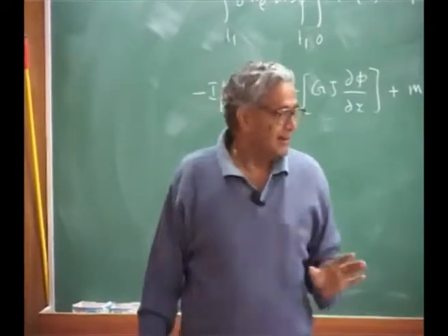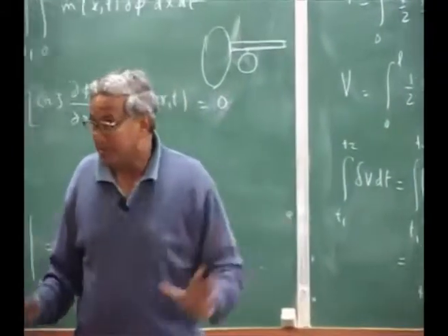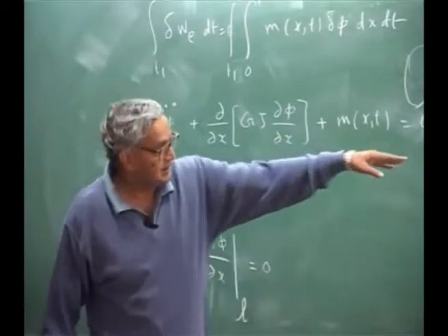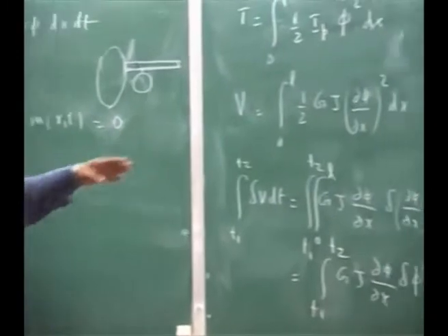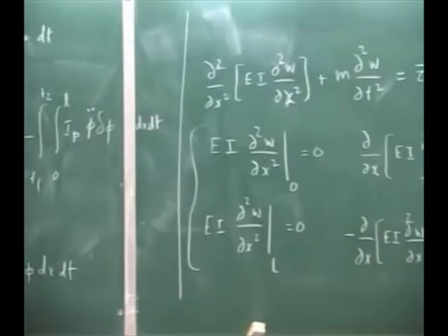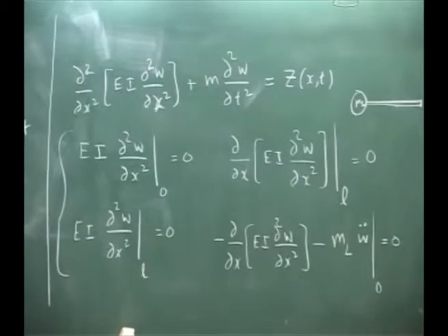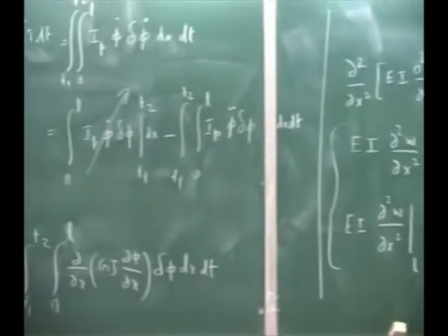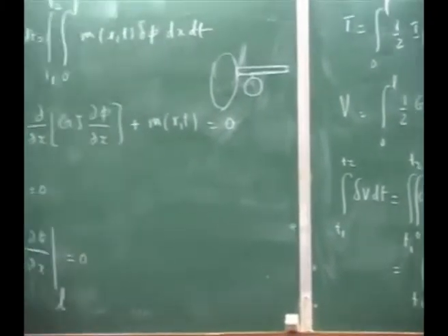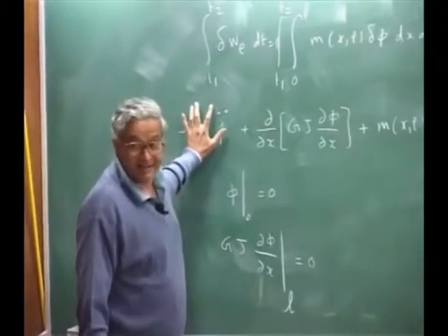Okay. So for really analyzing these problems, please understand, I have an external loading sitting here. If you say lift, that lift is there, and this is the moment on the wing. Both are sitting in the problem. But how do I solve this entire problem, because I have a time derivative also? Suppose it is a static problem, only wing deformation under a load, and I am not bothered about the vibration. That means this term is gone.